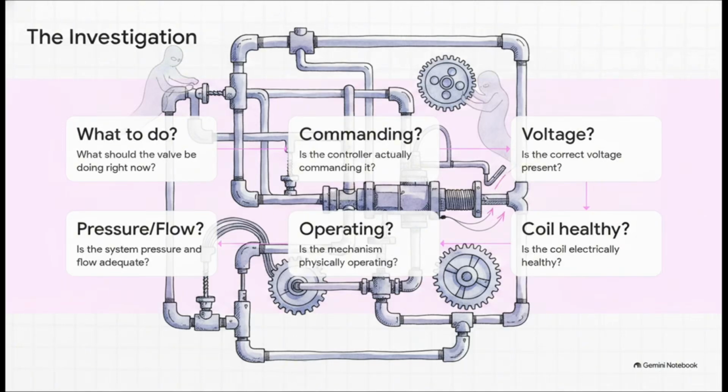1. What should the valve be doing right now? 2. Is the controller actually commanding it? 3. Is the correct voltage present? 4. Is the coil electrically healthy? 5. Is the mechanism physically operating? And 6. Is the pressure and flow adequate?